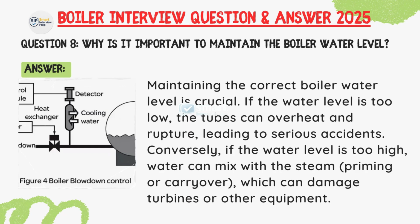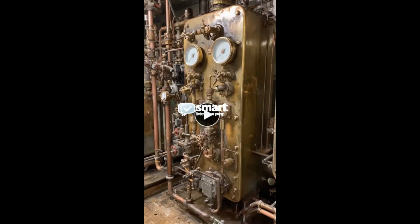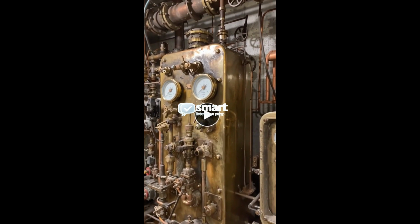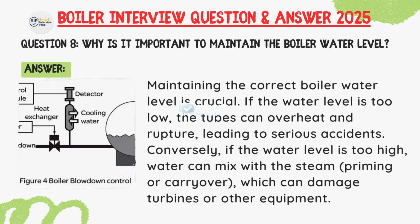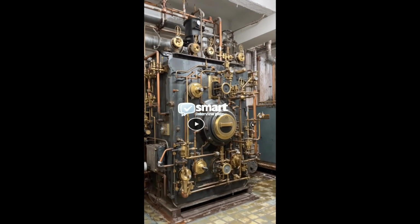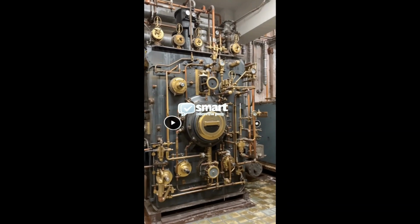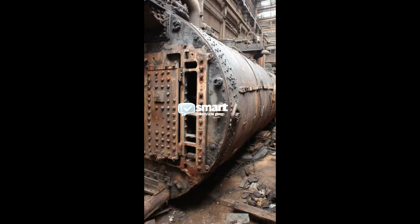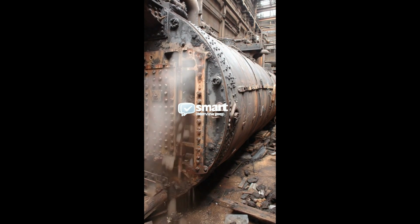Question: why is it important to maintain the boiler water level? Answer: maintaining the correct boiler water level is crucial. If the water level is too low, the tube can overheat and rupture, leading to a serious accident. Conversely, if the water level is too high, water can mix with the steam, causing priming or carryover, which can damage the turbine or other equipment.